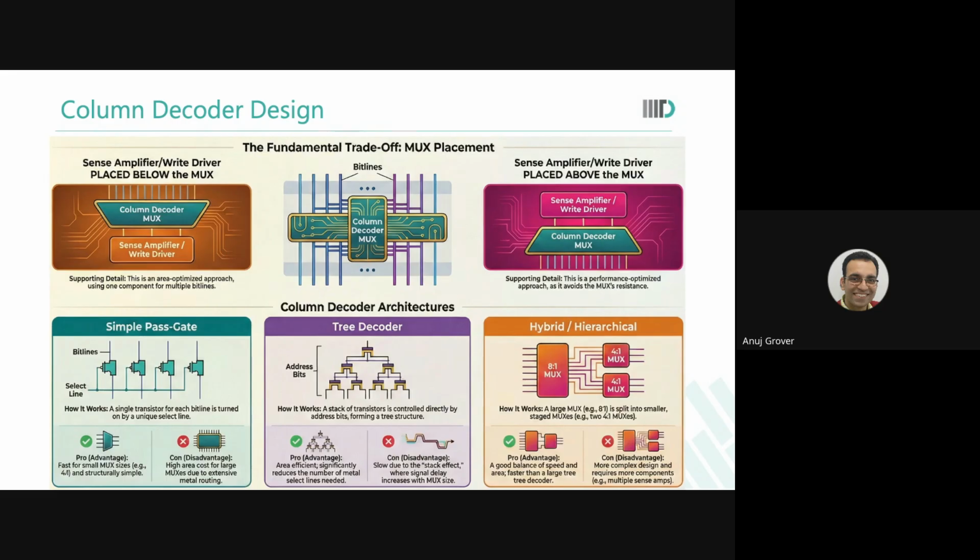There are two ports, port A and port B. Let's talk about port B. Now port A was writing on the adjacent cell. So for the cell on which port B is writing, it is an unselected cell for port A. Its pre-charge is on. So port A's pre-charge has a short circuit path through the cell selected by port B into the write driver of port B.